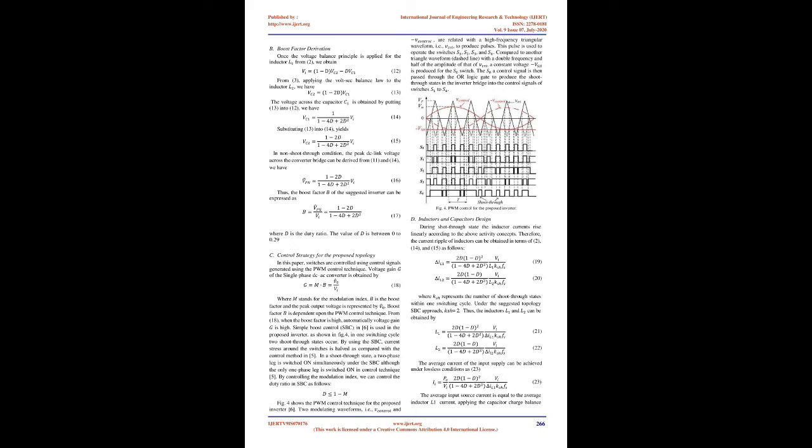A. Operation principles. For study purposes, there are 2 operative conditions of the proposed inverter, that is the shoot-through state and the non-shoot-through state. Operation principles of the traditional ZSI and the proposed inverter are similar. Fig 3a and 3b display the proposed inverter's corresponding circuits for the duration of the shoot-through and non-shoot-through conditions, accordingly. 1. Shoot-through state. When all the switches in any leg are switched on simultaneously, the inverter bridge is short-circuited, as shown in Figure 3a. This condition is called a shoot-through state.